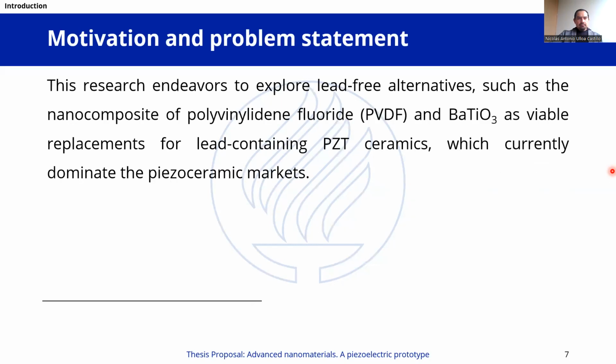This leads us to the first taste of what this research is focused on, where it endeavors to explore lead-free alternatives, such as a nanocomposite of polyvinylidene fluoride, which is also known as PVDF, and barium titanate. These are viable replacements for lead-containing PZT ceramics, which currently dominate the piezoelectric markets.